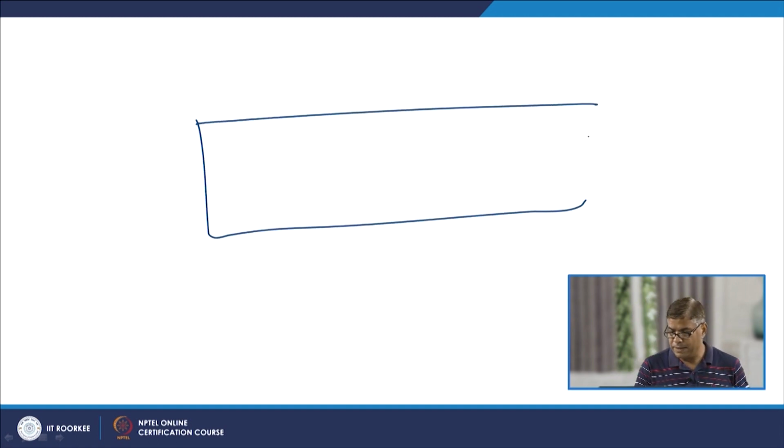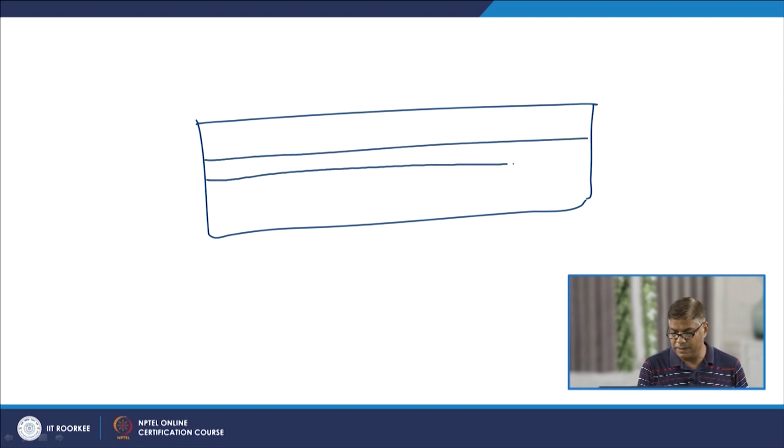But we must realize another aspect related to stainless steel: the stainless effect we are getting is due to the formation of a passive oxide layer, which is very thin and almost transparent. So, we are not able to see any effect of the chromium oxide layer which is being formed at the surface, but during heating or welding, when external heat is applied.